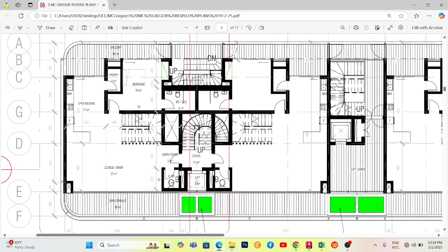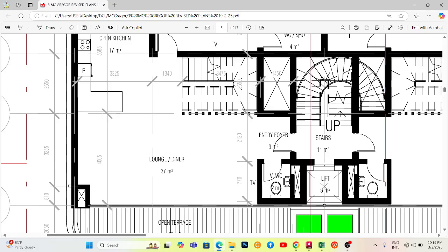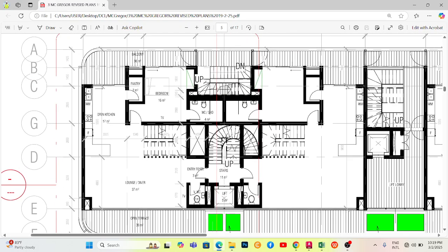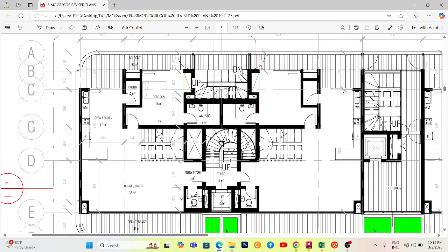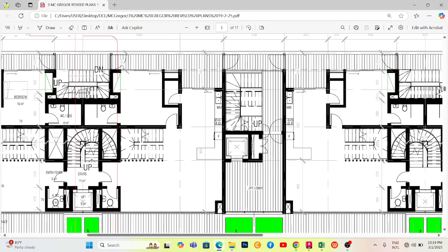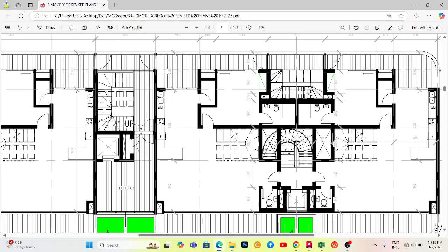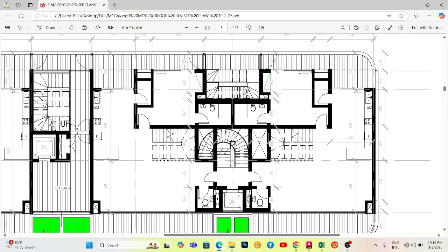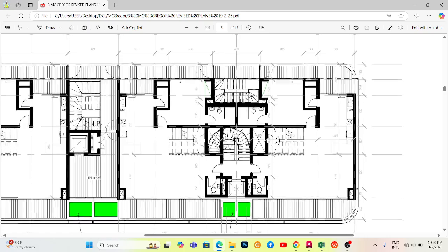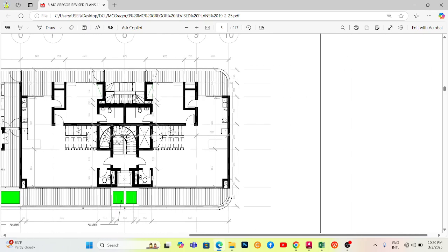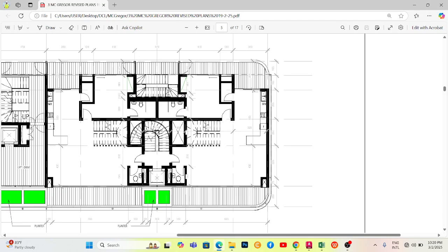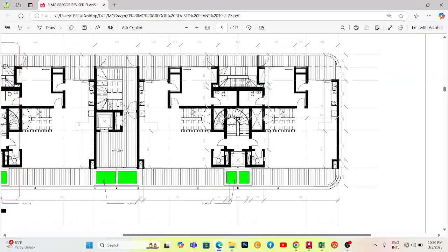So they will always give you your full dimension. As you are setting out your blocks, as the builder is monitoring the block setting out, you're always focusing on the dimension to make sure that you are getting the exact dimension as it is designed. Then one thing we always used to do is once we do our forming on the concrete on the ground floor, let's say on the first floor for example, we always invite the structural engineer to come and check after the first course, the first phase of the blocks. Once we've laid the forming, the foundation, we will ask them to come and check, we'll measure together, take physical measurements, then we verify, then he approves and we go ahead from there.